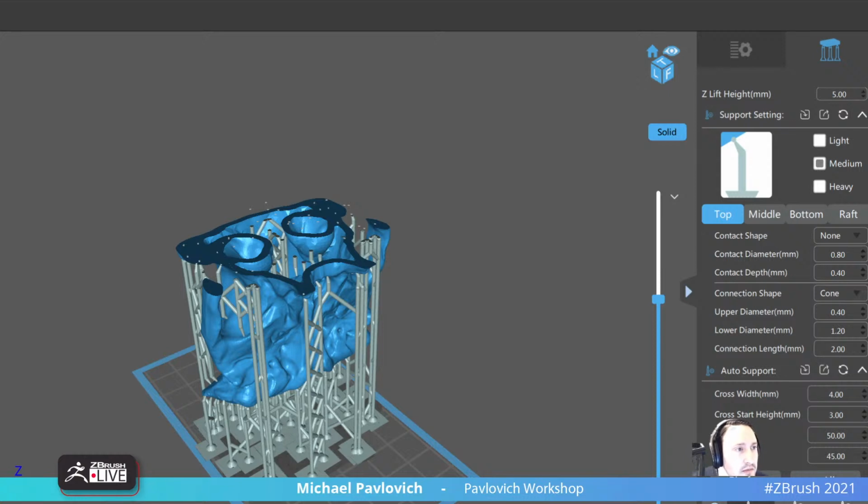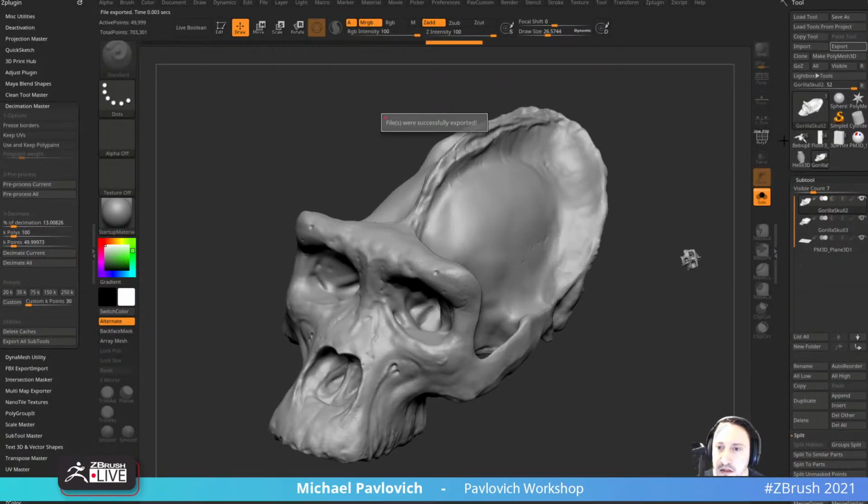Can't figure out how to use Dynamesh for things such as human feet. The toes really stick together. And if I use polygroups, then the groups get separated from the main body. Yeah, so what you're going to want to do is not use Dynamesh past a certain point. Dynamesh is fine for, do we got a model with feet?